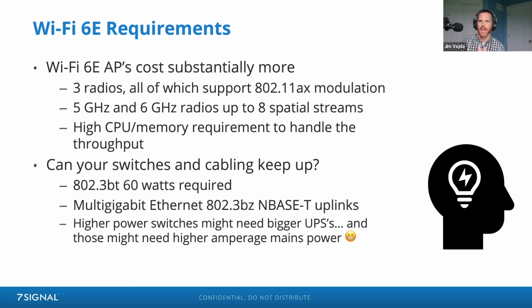And then there's this cascade of requirements, right? If we have a bigger power budget from our PoE requirements on a switch, and we have a requirement, say in a hospital, to have a UPS that powers that switch for an hour, or somewhere else that might have a requirement like that, then that switch has a higher power draw, and we might then be required to upgrade our UPSs in the IDF in order to meet our backup operation requirement.